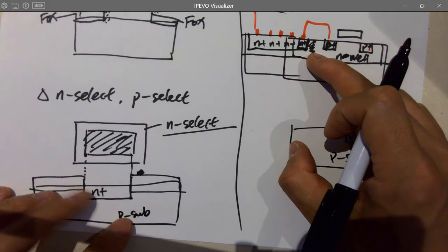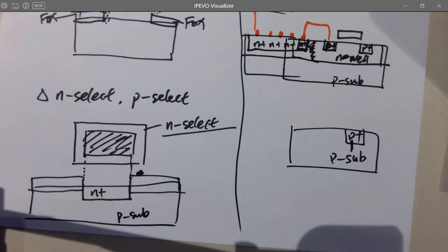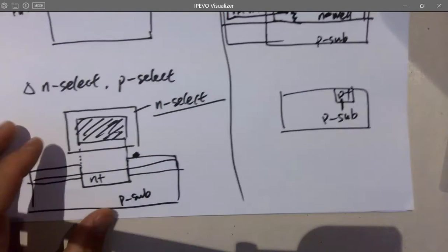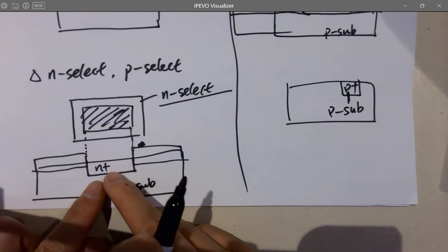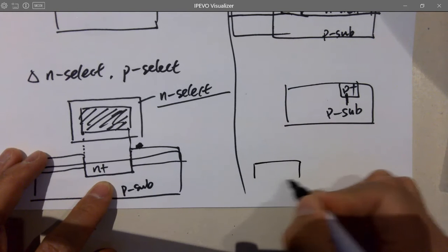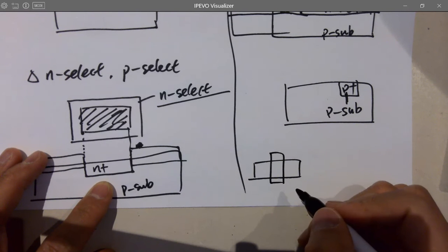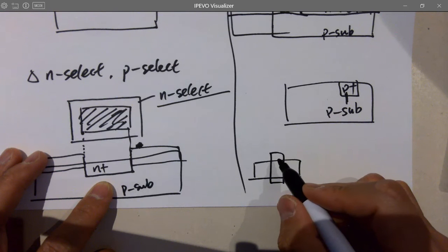Okay. So the NMOS, if you look at the shape from the layout view, you can notice that PMOS and NMOS have different colors, and some of them are slashes, some of them are dots, right? I remember the yellow slashes are the P sub, and the black dots are either N plus or P plus, I forgot, but you can pay attention to it on Tuesday and take a look at it. And also, look at the diffusion, so you can grab an NMOS, right? Remember, that's a little NMOS. Does it have a contact? It doesn't.